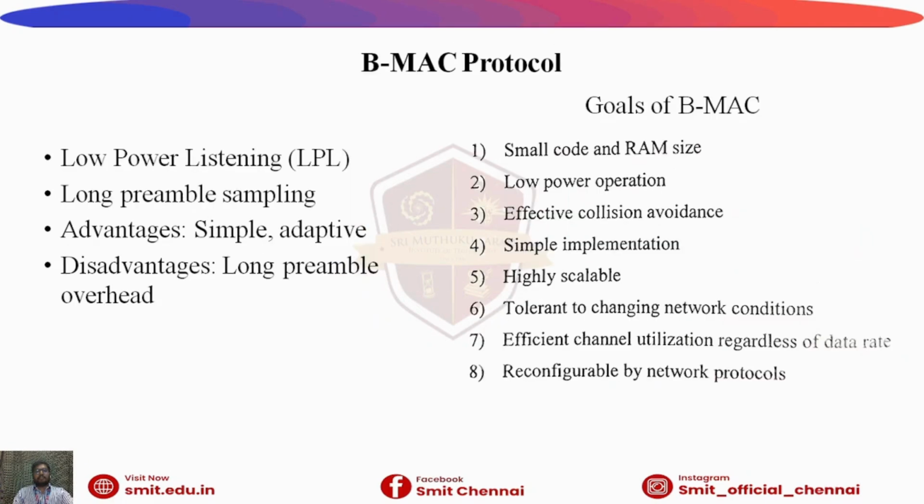Next protocol is BMAC, which means Berkeley MAC, a highly flexible and simple protocol. It uses low power listening (LPL), in which the nodes periodically wake up and sample the channel. The transmitter sends a long preamble so that the receiver detects it during sampling. Advantages of this protocol are that it is very simple to implement and has an adaptive duty cycle.